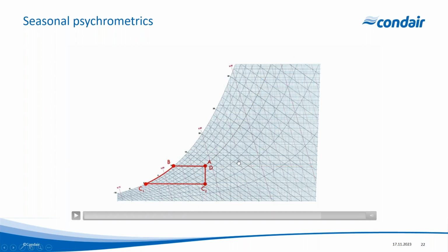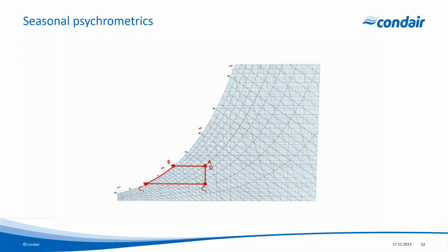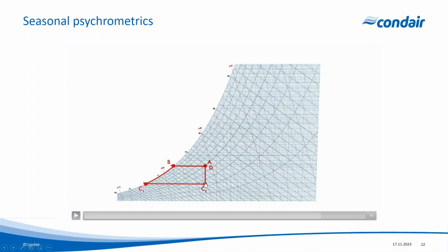So this is what that looks like. We have a start condition where we're controlling an environment at 21 degrees C and 50%. As that air is cooled down at night time, and we take outdoor air, it cools down, gets to its saturation point, gets even colder, and moisture is released. We then have air at 100% saturated and 0 degrees C. And when we heat that air up back to 21 degrees C, we have to then humidify to get us back to 50% RH.